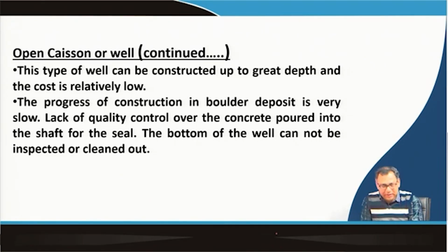But the disadvantages are the progress of construction in boulder deposit is very slow, and the lack of quality control over the concreting, because the concreting is done underwater. So, quality control over the concrete poured into the shaft for the seal is very difficult. The bottom of the well cannot be inspected or cleaned out. Because the bottom is under the surface, it cannot be inspected properly and cleaned out.